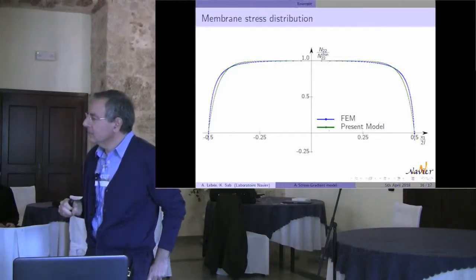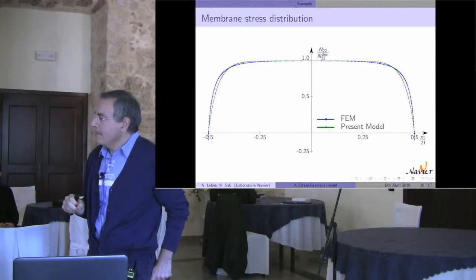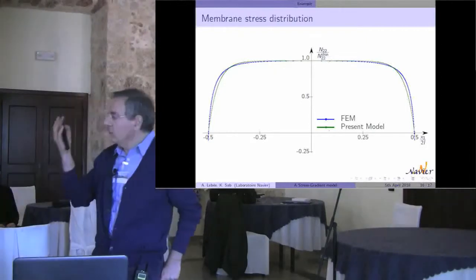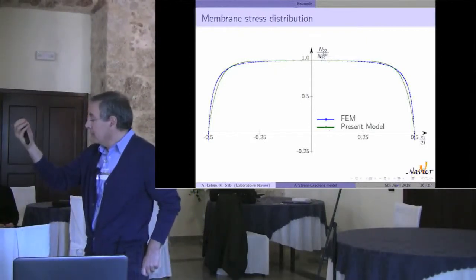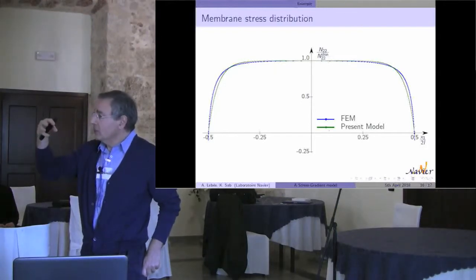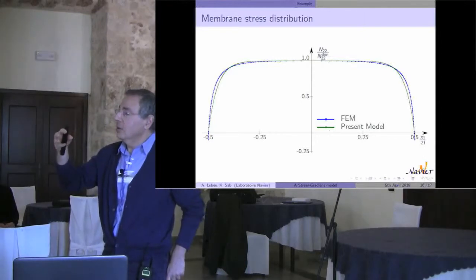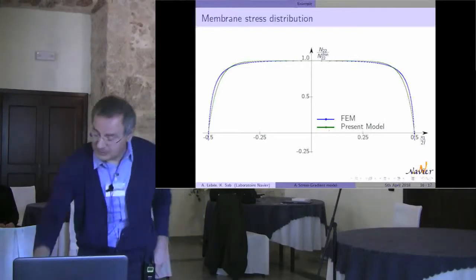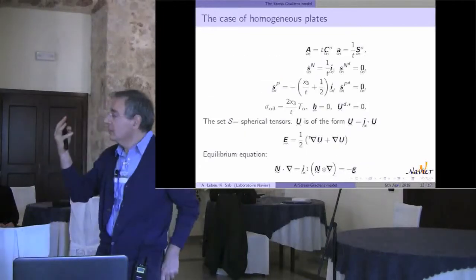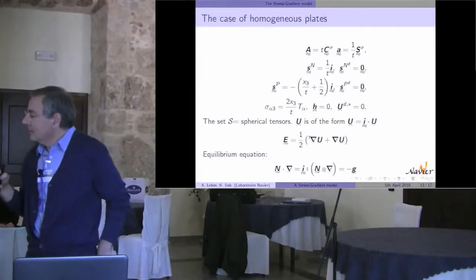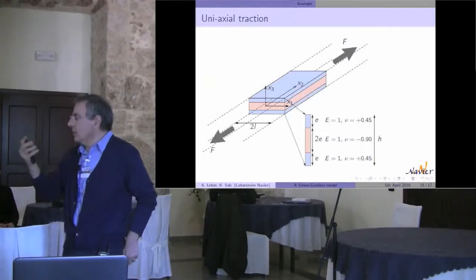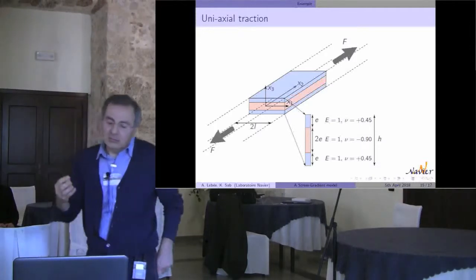In the example, the contrast coefficient is very small. If you have a contrast ratio of, let's say, about 0.1, is the effect still there? I think that if the contrast is small, you will go toward the homogeneous material, and the effect of stress gradient will go to 0. This is rigorously shown here. These are preliminary results, and we should try much more